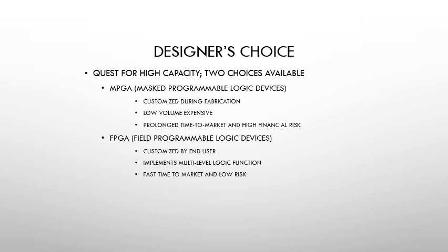In the designer's choice, first of all we choose MPGA or FPGA. MPGA means mask programmable gate array. It has some features: it is customized during fabrication, low volume and expensive, with prolonged time to market and high financial risk. After that we are going to see the FPGA.